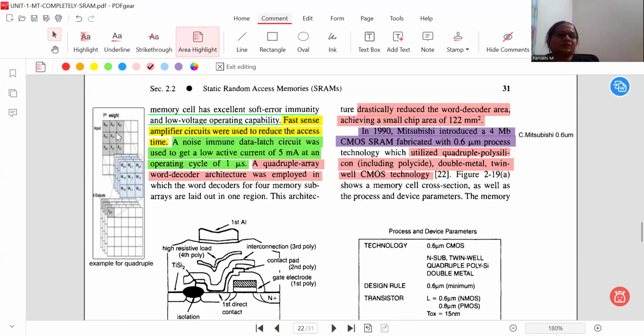Like that, in the given structure, the decoder windows go from one window to the other, instead of considering the decoder completely line by line with AND gates, which causes more area to be occupied. But here, the array windows are connected one after the other in such a way that it takes very little area, and the resolving of each window access happens by intermediate sub windows.